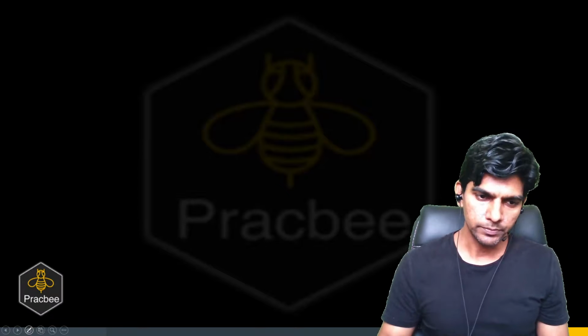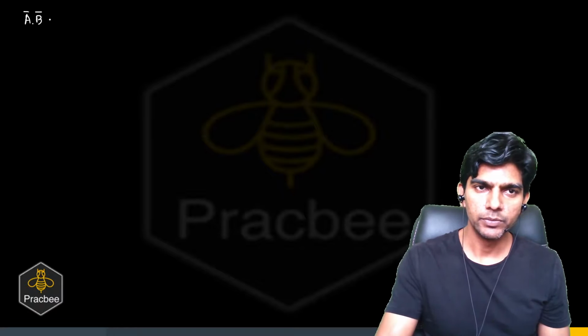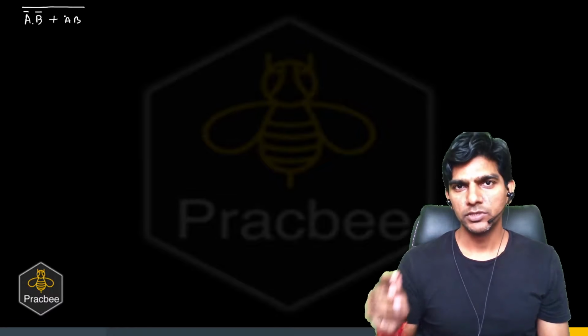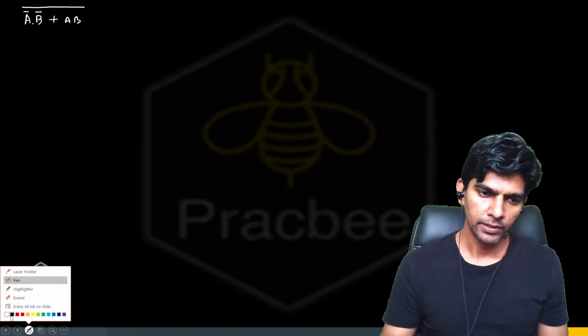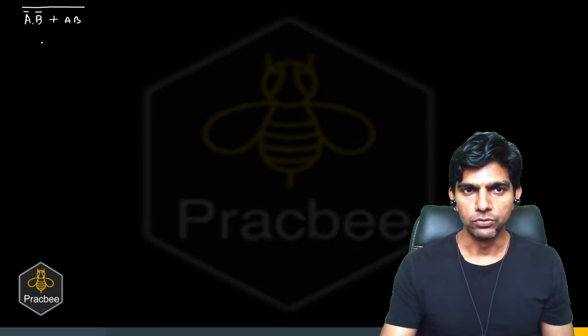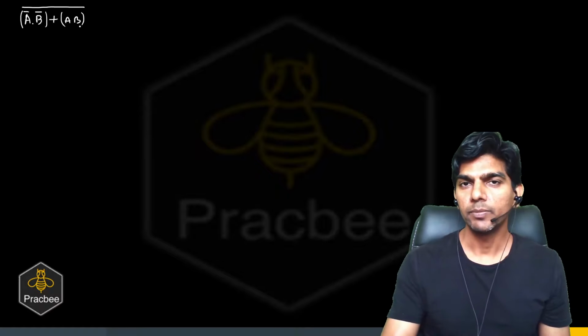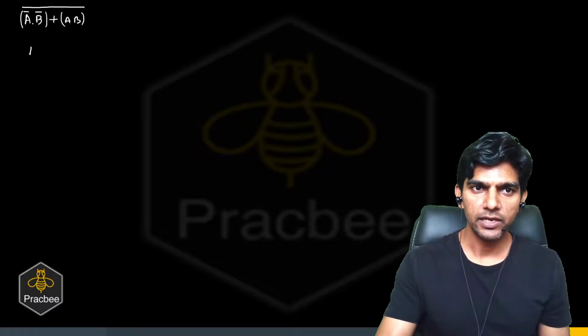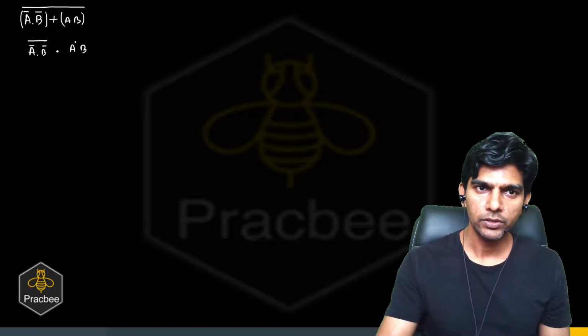So let me give you a question. Suppose we are given (A multiplied by B, whole bar) multiplied by (A bar multiplied with B bar plus AB, whole bar), right? Just pause the video and try to solve this question on your own. Okay, so let us see what we can do. If I consider these as two terms and apply De Morgan's theorem, this can be written as (A bar dot B bar) whole bar multiplied with (AB) whole bar.